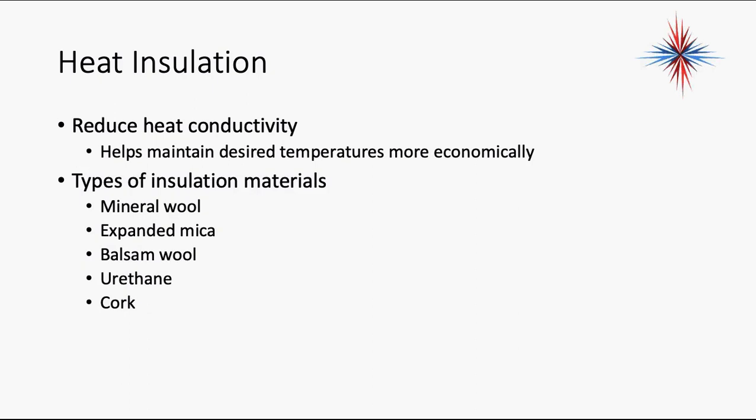We also have the spray-on foam insulation that's becoming more and more popular. And over the last couple of years, I've also seen an increase in them mixing insulation right into the concrete, right into the brick material that they're using to build foundations and stuff. So the insulation has changed over the years as well. What they're doing is everything is becoming tighter. Well, the tighter houses are great for energy efficiency, but they're not all that great for air quality. And that's where we're going to do more discussion after we talk about air distribution and pressures.